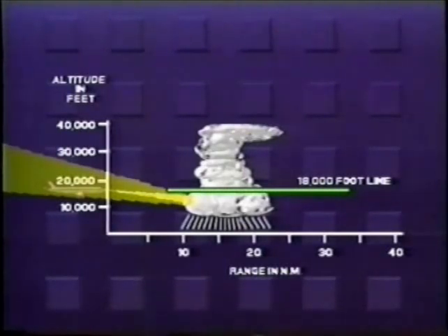At the higher altitudes, it's important to remember that you are flying above the most reflective part of the storms, and consequently, you will require a significant down tilt to make certain no storm goes undetected. If you ever find yourself in doubt about whether or not the tilt position is correct after you have made a range change, move the tilt angle down briefly and readjust the beam to give the correct amount of ground return. The best way to develop good tilt and range management skills is to practice them in good weather. Once you have gained these skills and refined them, it will be a simple matter to adjust the tilt and range controls for safe weather avoidance.